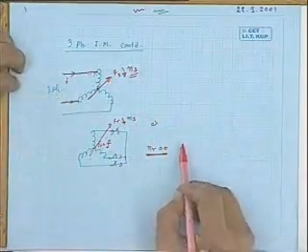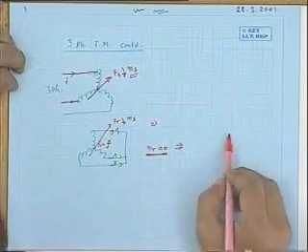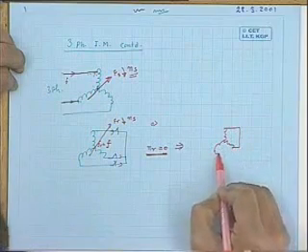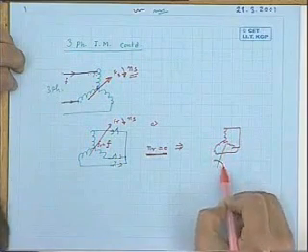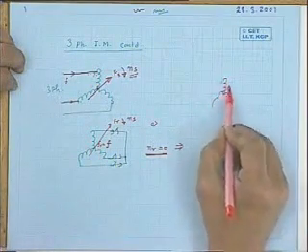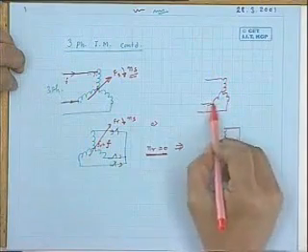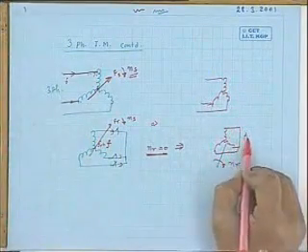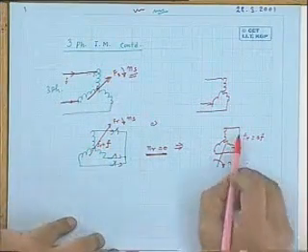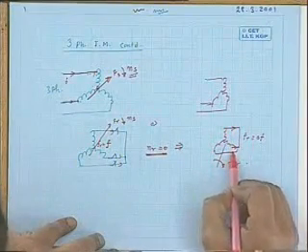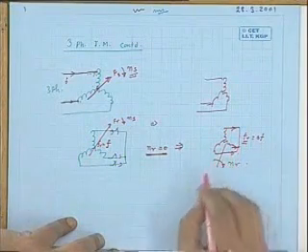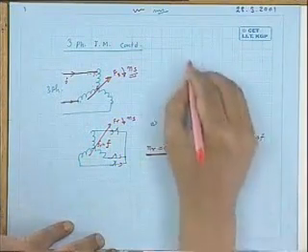Now, this is also true when the rotor is running. What I am trying to tell: suppose the rotor runs with some slip, that is, it is closed, and the rotor mechanical speed is suppose nr, and suppose the stator is supplied from a balanced three-phase supply. In this case, what is the rotor frequency? Fr is sf. So the frequency of the rotor current will be this frequency Fr. What will be the speed of the rotor field?